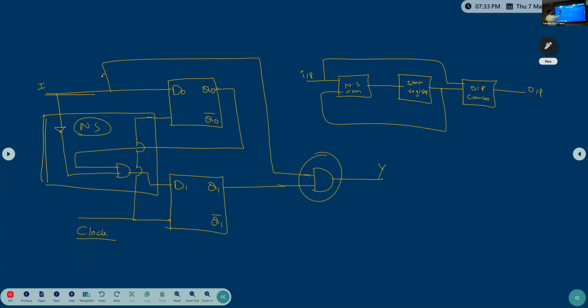So the output is directly connected to the input, right? Yes or no? If the input changes, the output changes immediately. That is fast, but when the input changes and the output changes immediately, it can create noise in the output signal, and that is the problem. Clear? So this is the circuit. Definitely in Mealy machines, the input I should be connected to the output. Then only the final circuit is correct. Otherwise, you did something wrong.